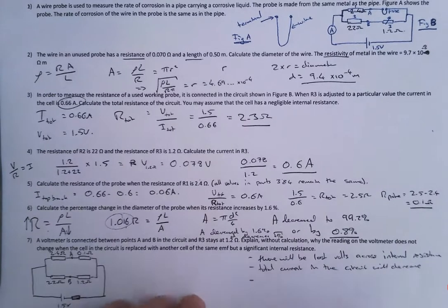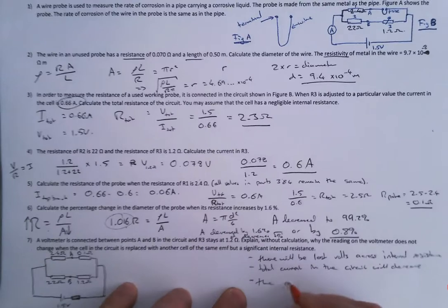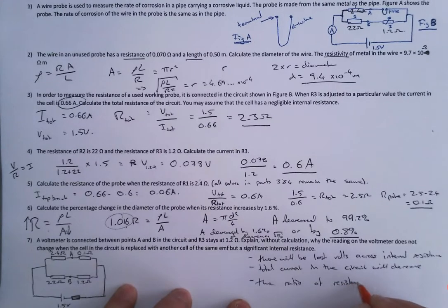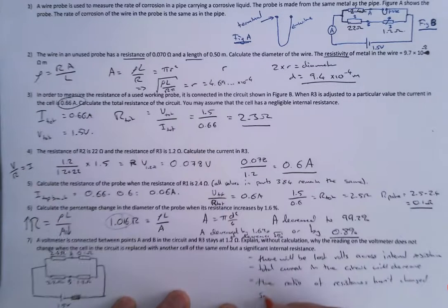But what hasn't changed? The ratio of resistances in this top section here hasn't changed. So the PD from A to B remains the same.